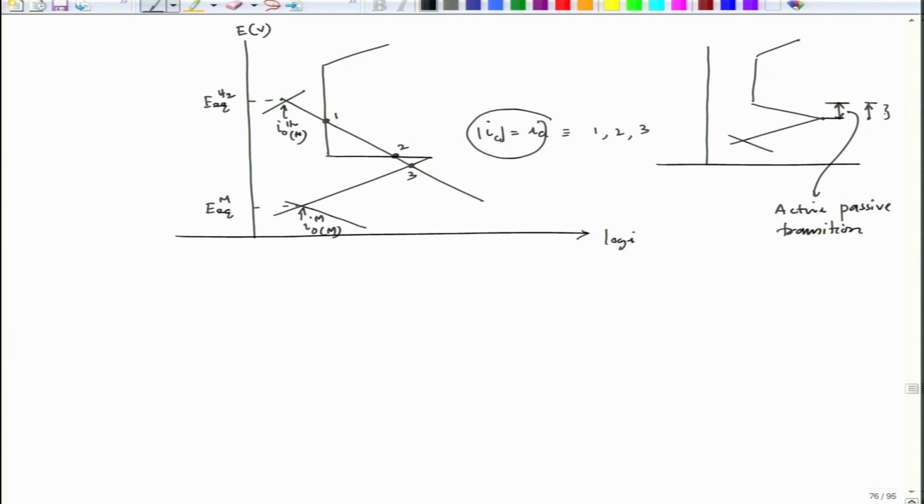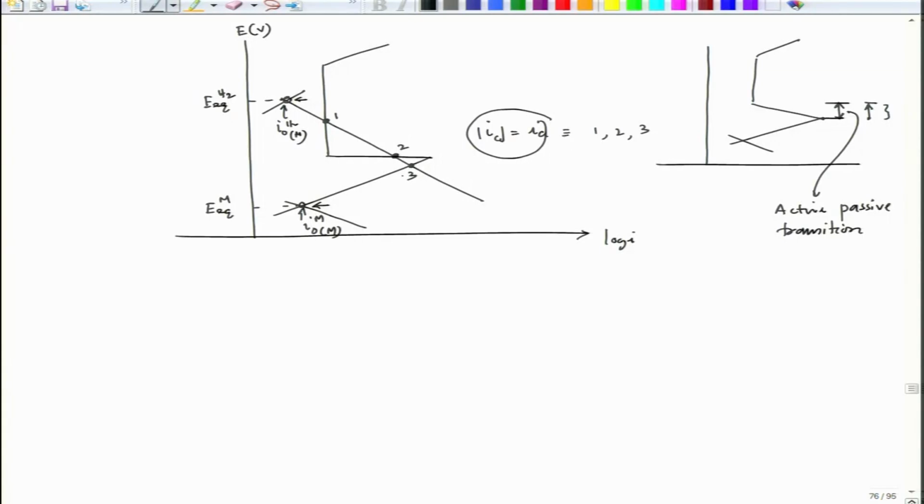Now, when we are dipping that active passive metal into an acid medium, and if it is a freshly prepared metal without having any oxide surface or hydroxide surface on that particular metal, the metal will be at that potential. So, this potential and this potential, these two potentials will try to drag those potentials downwards and upward to reach that mixed potential position, and it is a freshly prepared sample, so we do not have any pre-existing oxide layer. In that case the system will try to find the first location where mixed potential theory is satisfied.